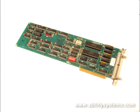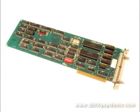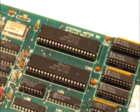Some indexers consist of a controller card like this one. To use this card, an application program communicates commands to a microprocessor located on the card. The card's microprocessor, in turn, generates the pulse and direction signals necessary to direct the translator. Other manufacturers may use an external circuit that receives commands from the application program by means of a serial port. Some manufacturers even package the indexer with the translator.